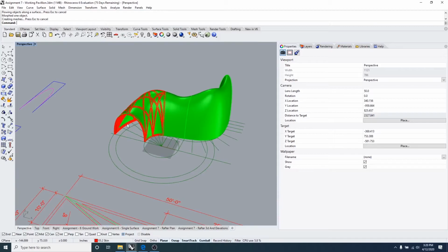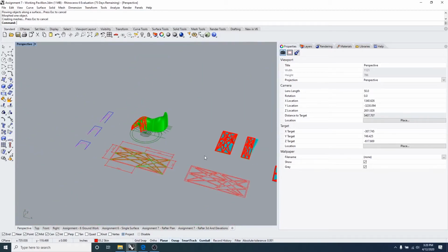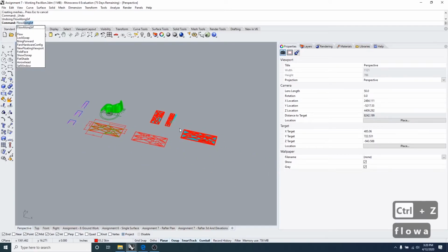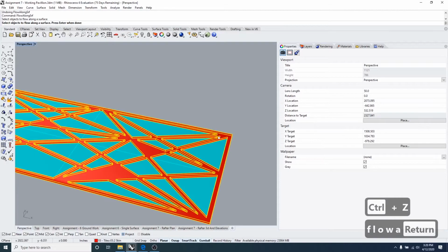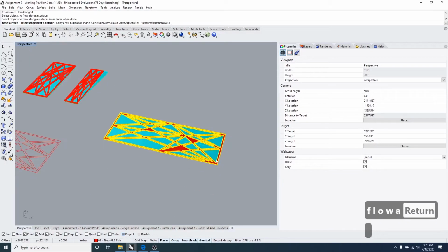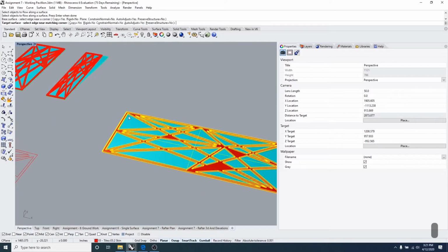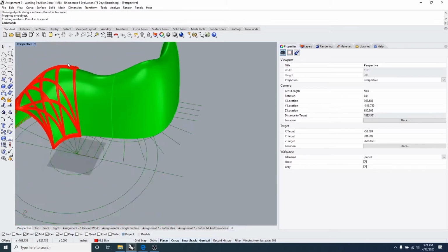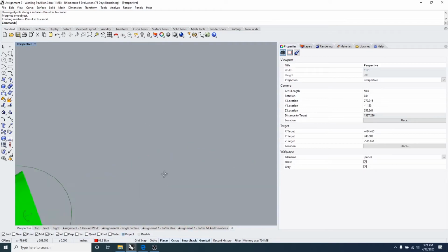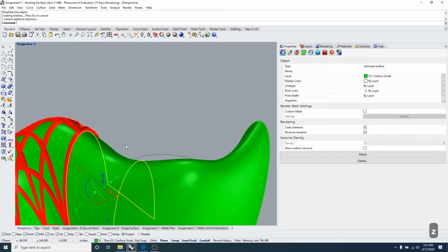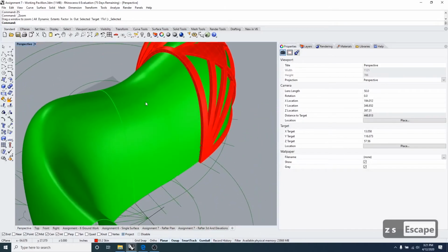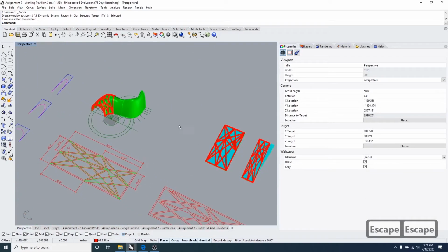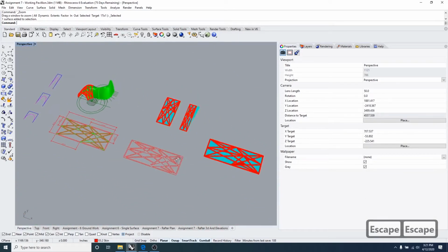And then you guys can see that it went on the inside. That means I'm on the wrong corner. So I'm going to do it again. I'm going to say flow along surface, select my panel, pick the next corner, and I'm going to pick this corner. And notice how now it actually goes all the way to the panel itself. So we're going to do it that way rather than the whole create UV curve.